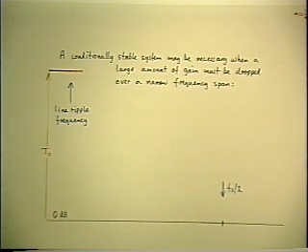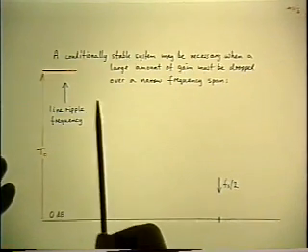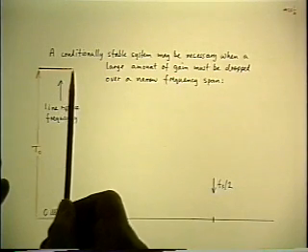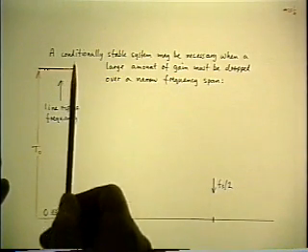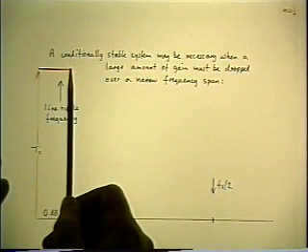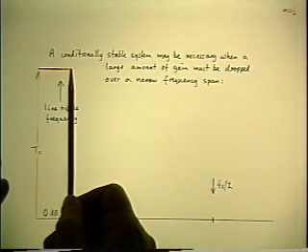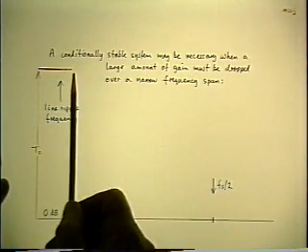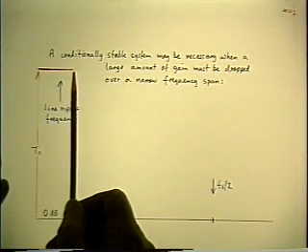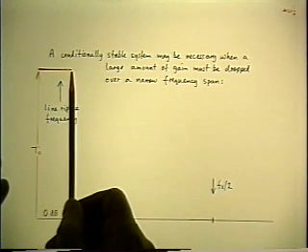And suppose you need 40 dB of feedback over that entire range in order to keep the speaker damping factor high over the same range, in order to keep the distortion reduction high over the same range. In other words, your specifications may involve a minimum value of loop gain that you need at some low frequency. So say this might be 20 hertz, and you have a specification of a minimum of 40 dB of feedback at 20 hertz.